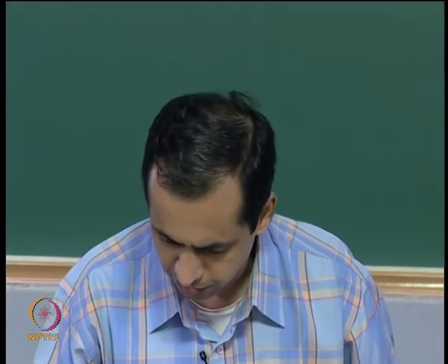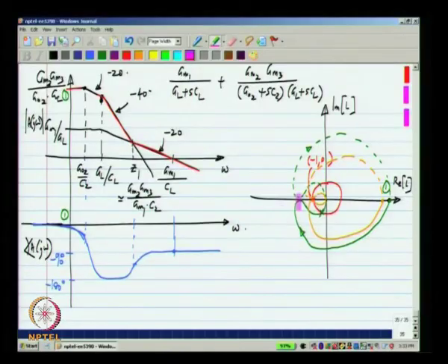As I said earlier, we derived conditions for stability, and not only stability, stability margin, that is good behavior without a lot of ringing, based on our analysis of systems with ideal delays and low order systems like first order systems and second order systems and so on. And we saw that if you have a large phase margin, you will generally have a step response which does not have ringing. Okay. So, in this particular case, if you enclose this op amp in a unity feedback loop, and if the op amp's transfer function happens to follow this green curve, then there will be no significant ringing, and if it follows this orange curve, you expect that there will be a lot of ringing. Okay. We will confirm this by explicit analysis.